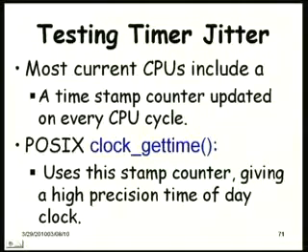But what you are interested in here is the difference between two times. It is not the clock time, it may be a large number, not bothered about that. You have to take the difference. First take the clock reading and then keep on taking the readings each time the interrupt occurs. Take the difference and that will tell you how much time has expired since the interrupt has been reported.